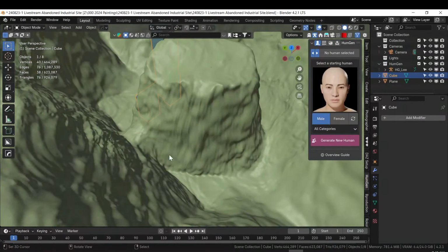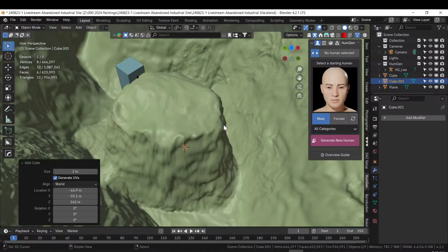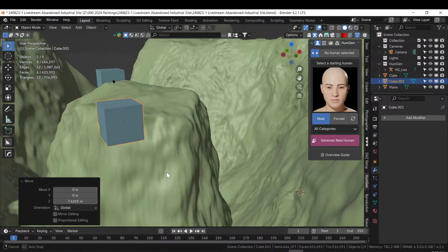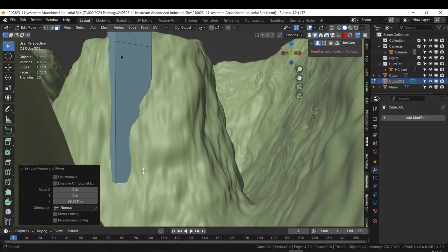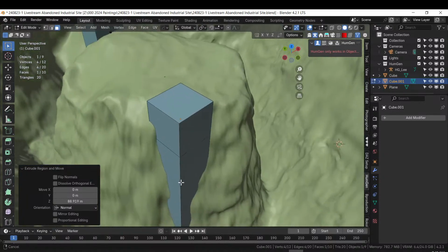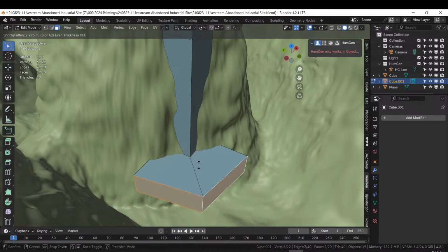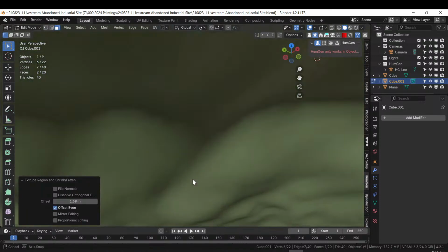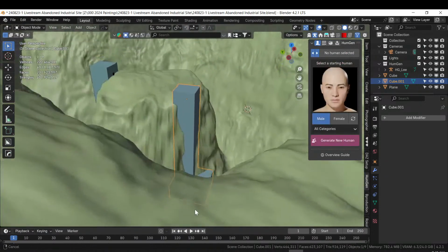I like it. Let's kind of do the same thing over here. Mesh, cube again, S12. Cool. Tab, E. Ooh, I like that, it cuts in better. That's actually nice. E, grab this face and this face. Alt E along normals. Out to there. Let's go with even. Cool. And I think we'll leave that off the ground.